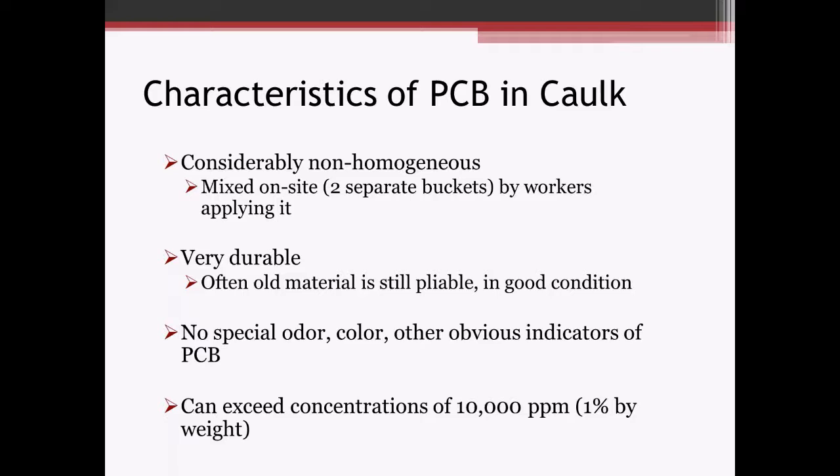There's no special odor, color, or other obvious indicators of PCB. So that makes it a little difficult when you're doing a cleanup project, especially with soil material that might be contaminated. You really don't know where to end until you sample. You remove some soil, you sample. If you're high, you remove more soil. You really can't see it in those scenarios. So that makes it tough, and no real odor on it.